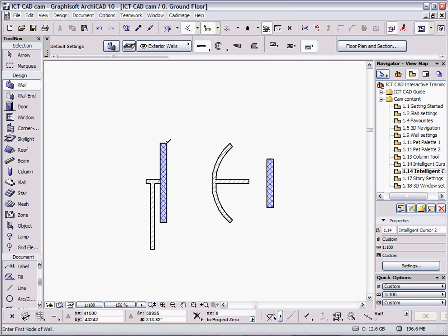The other symbols that we see are tick marks. If I put the mouse onto the end of this wall, it's a thick tick mark, that means it's the outside corner point. If I go to the inside, it's a thinner tick mark. Same at the opposite end, and also in the middle. This midpoint is defined by the special snap geometry, and that's set down here currently as half, but if I was to change this to divisions of 4, then I've now got 4 divisions along the outside of the wall, which the cursor will actually snap to.